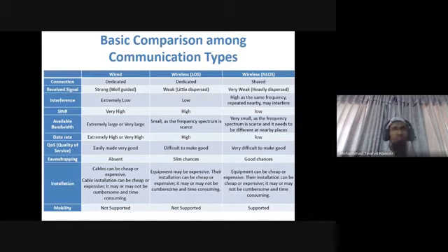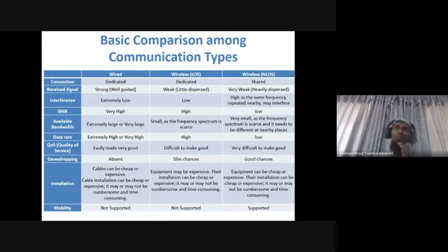In the case of LOS, since you know the location of the receiving antenna, you try to confine the radiated power in the air as much as possible. It is not completely confined, but it is pretty well confined. Since it is well confined, it is little dispersed. You get a signal which is weaker than the wired case, but stronger than the non-LOS case.